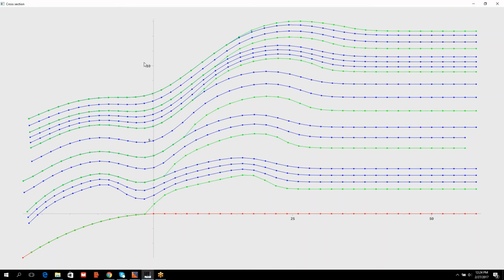If we look, for example, at the third lamina here, which is between the blue lines, we can observe that the layer thickness may be slightly smaller or greater than the nominal thickness while we go over the previous turning points. Some sort of smoothing is needed to guarantee a proper mold surface for the following lamina. This phenomenon can be observed later from the FE model.